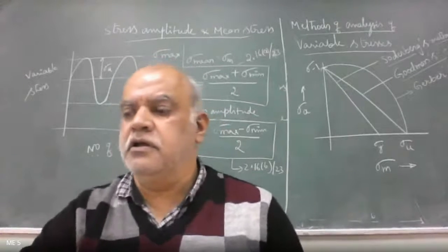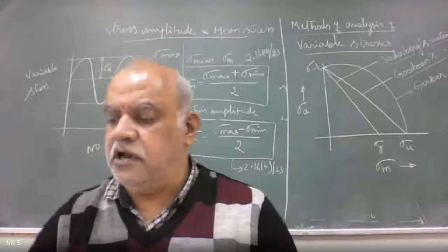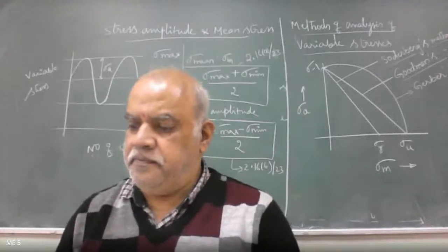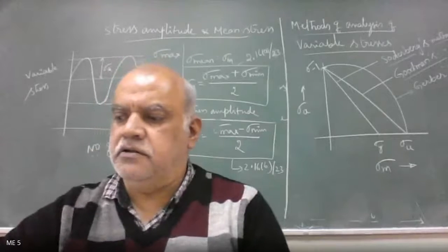Tarun Pachori, please read out the definition here clearly. Others, please follow. It is defined as the maximum stress which a plain specimen can sustain for 10 to the power 7 or 10 to the power 8 cycles without failure. Without failure. Okay.